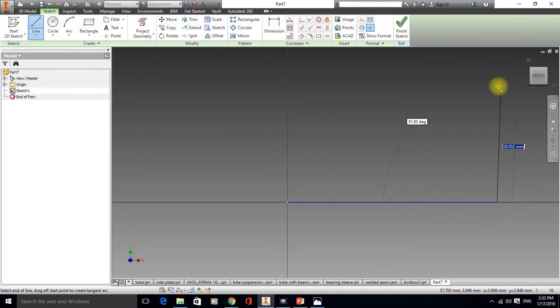Now I'm going to go vertically, and you can see it's actually put on a perpendicular constraint now. So if you look at the bottom line, you see the horizontal constraint and the perpendicular constraint. Alright, just going to click OK. You'll see this line's gone purple, which means it's fully constrained. This line's green, which means it isn't constrained. I'm just going to undo that and start again.